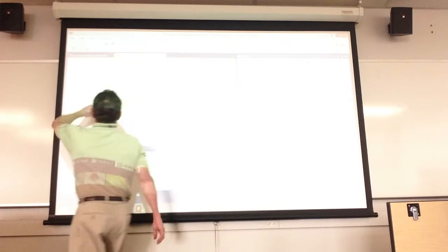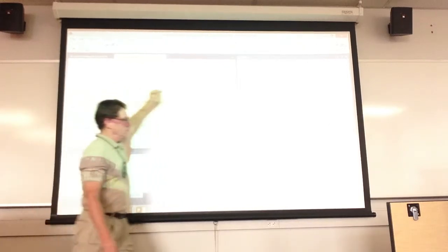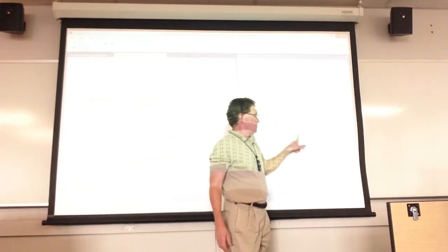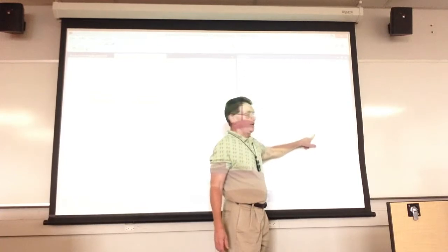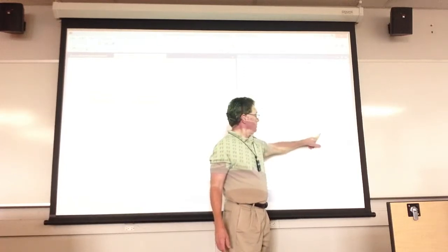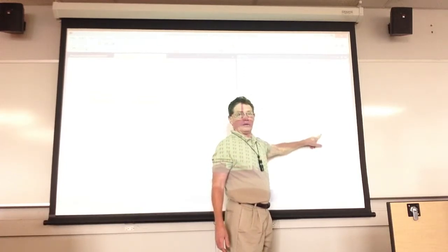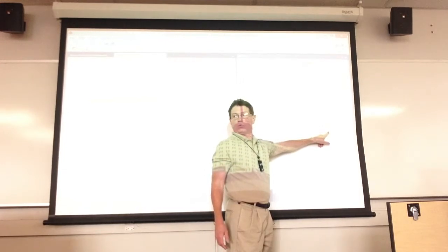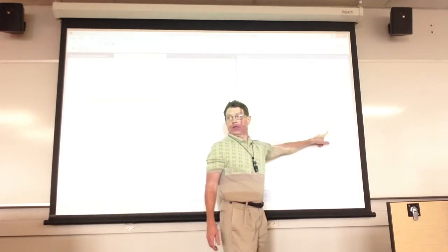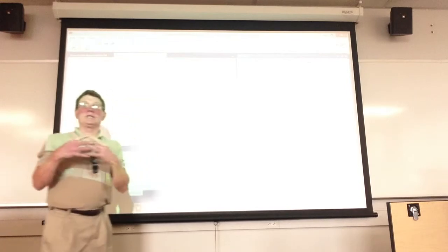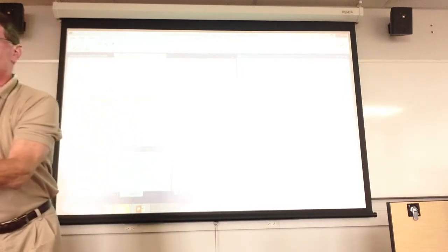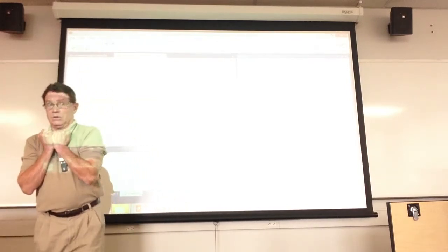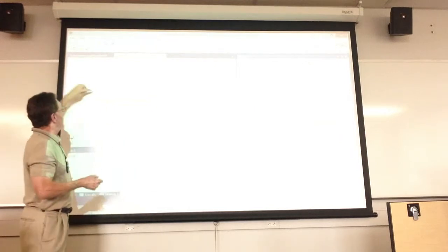And then we're going to output some bits to port C now. You're going to see that bit pattern that we set up here. Pin 7 is high. 6, 5, 4, 3 are low. 2 is high. 1 is low. And the 0th one is low, or high. Okay? So that's just the data that I want to set up on port C to read in. All right? So that's the reason why I had to do this.